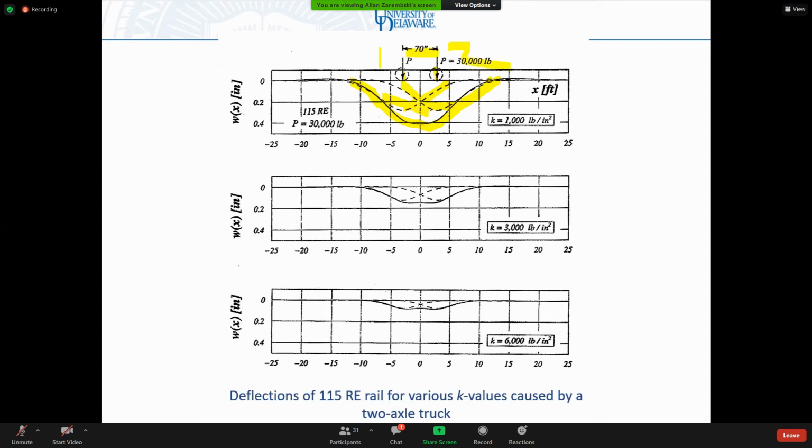At x equals 0, in this particular case, they're about the same value, about 1/4 inch. I've got 25 millimeters to 1 inch, so 1/4 inch is about 6 millimeters. So I have 6 millimeters from one curve, 6 millimeters from another curve. I add it up, I get 12 millimeters over here, and that's my combined deflection.